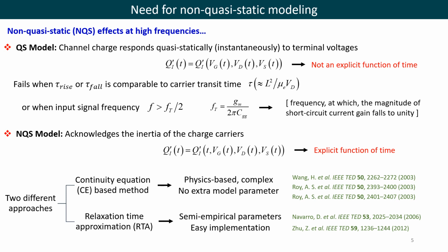An NQS model explicitly acknowledges the finite inertia of the charge carriers, and therefore all the relevant model parameters become an explicit function of time. There are two approaches for non-quasi-static modeling. First, the current continuity equation based model, and the second one is the relaxation time approximation technique.